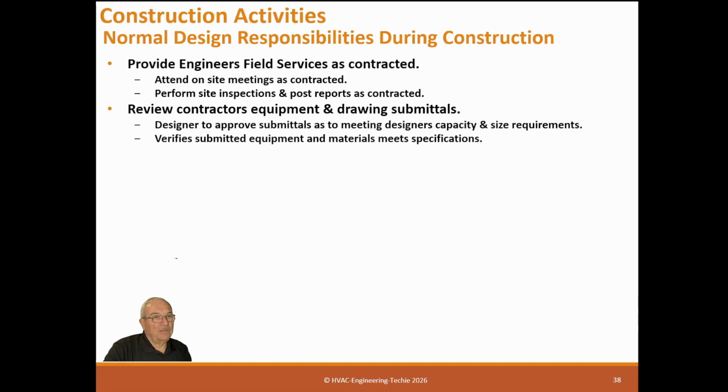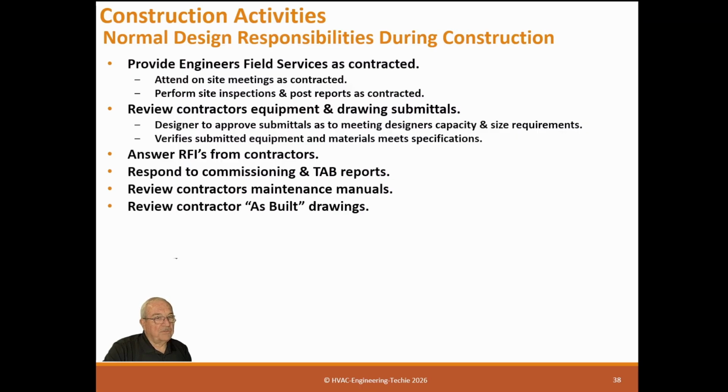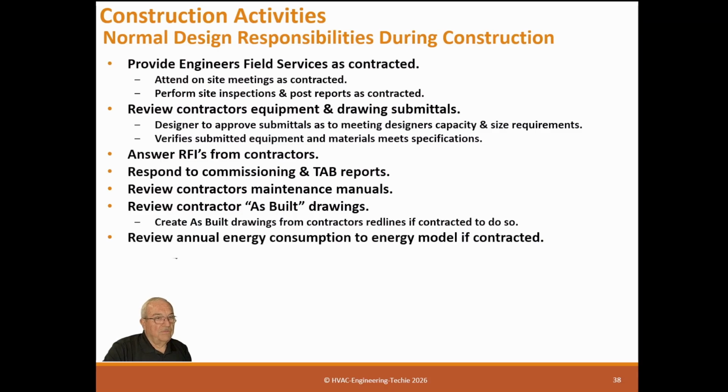Verify submittal equipment and material meet specifications, answer RFIs from contractors, respond to commissioning and TAB reports, review contractors' maintenance manuals, review contractor as-built drawings, create as-built drawings from contractor red lines if contracted to do so, review annual energy consumption and energy model if contracted to do so.